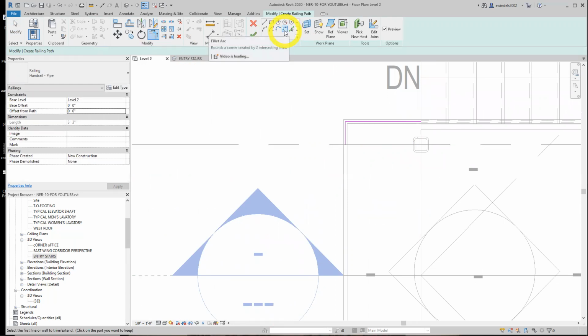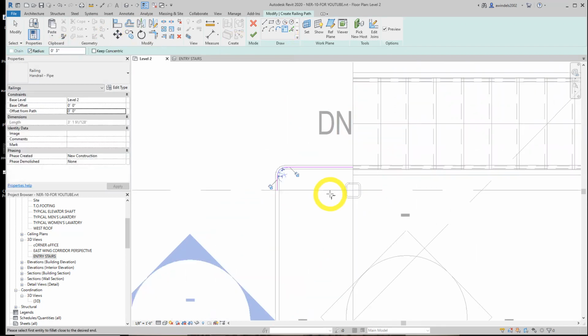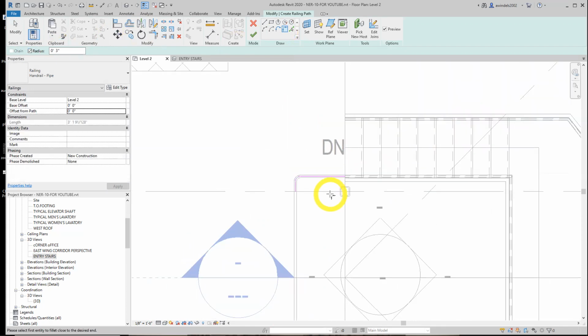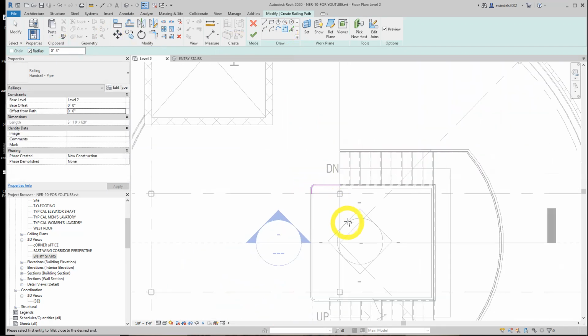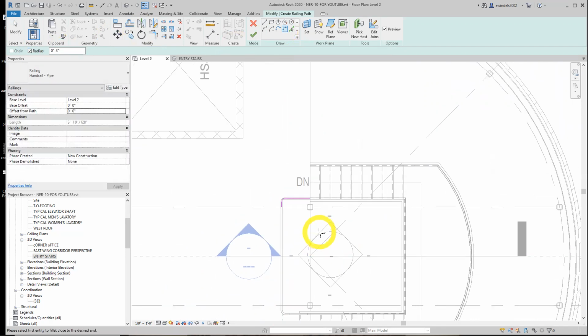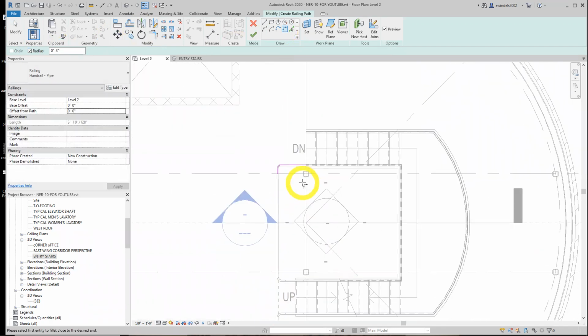Let's make a fillet arc. Let's make sure its radius is 3 inches. Click on this and check that. Should be good because you already have it done. Pick here, pick here. Okay. A lot of railings are good to do one at a time like this, not always continuously. The way the book's doing these is a pretty good method. That one's done.